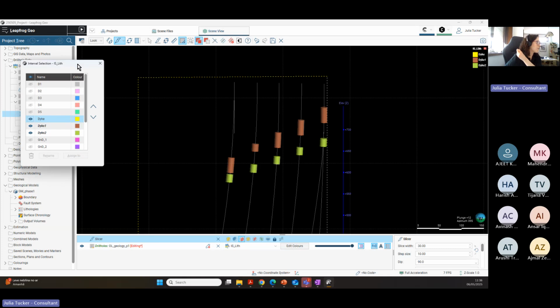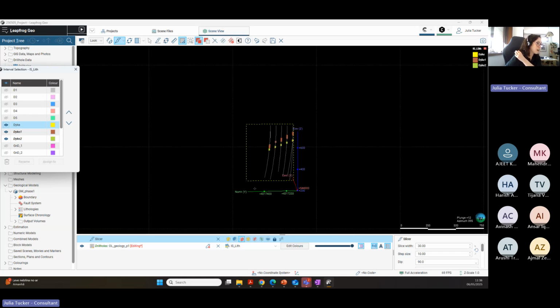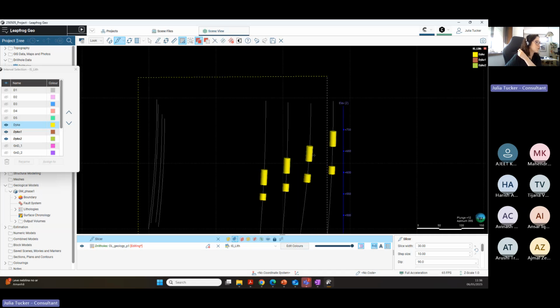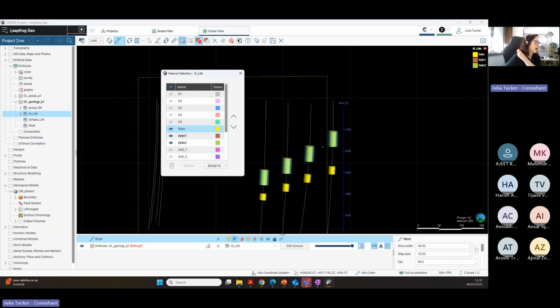So now we have done this for one side. We wanted to do this for the other sides. And I already have my slice here. What are my options? I can just come to the slicer that is right here, and I can click to see the other side of it. And this way, I am going to come closer again, and I'm going to select it all over. But this time, the other side, because I know there were two sides of it. And now I just need to assign to my dike 1 that I have already created.